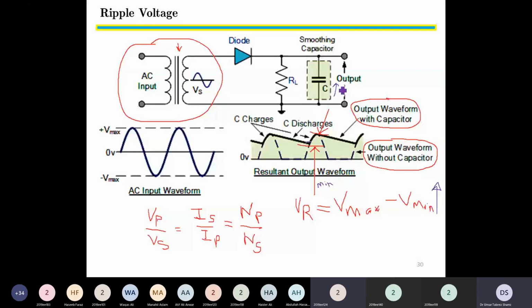Yes, I understand what you're saying, but it's not seconds if we are using a very heavy capacitor, since the capacitor is directly connected across the load. Therefore, if we disconnect the transformer, meaning we want to turn off our device, the capacitor will not allow RL to be turned off until it is discharged.